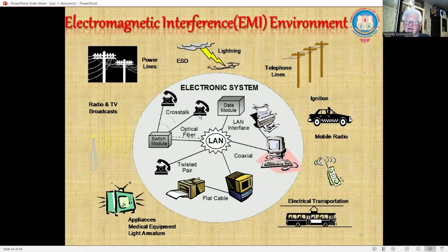Electronic units and their enclosures or boxes can be designed to have very efficient electromagnetic screening. However, the Achilles heel of the system can be the interconnecting cables which link together all the elements of the system. These interconnecting cables must have very efficient electromagnetic screening, which incurs a significant weight penalty.